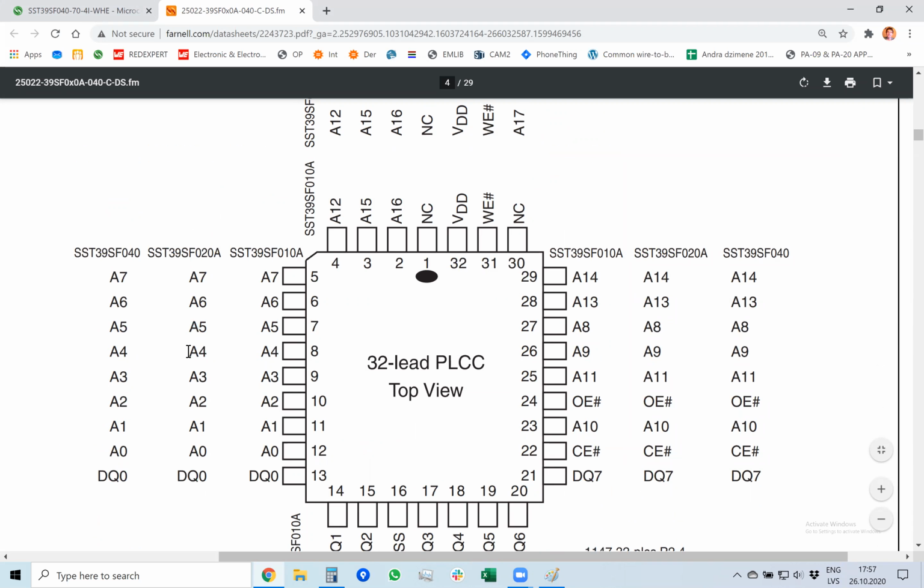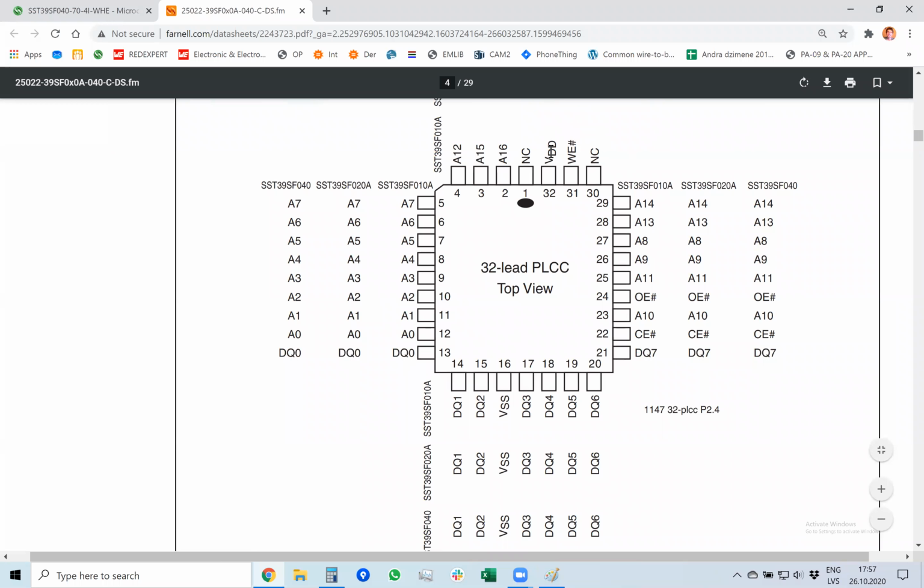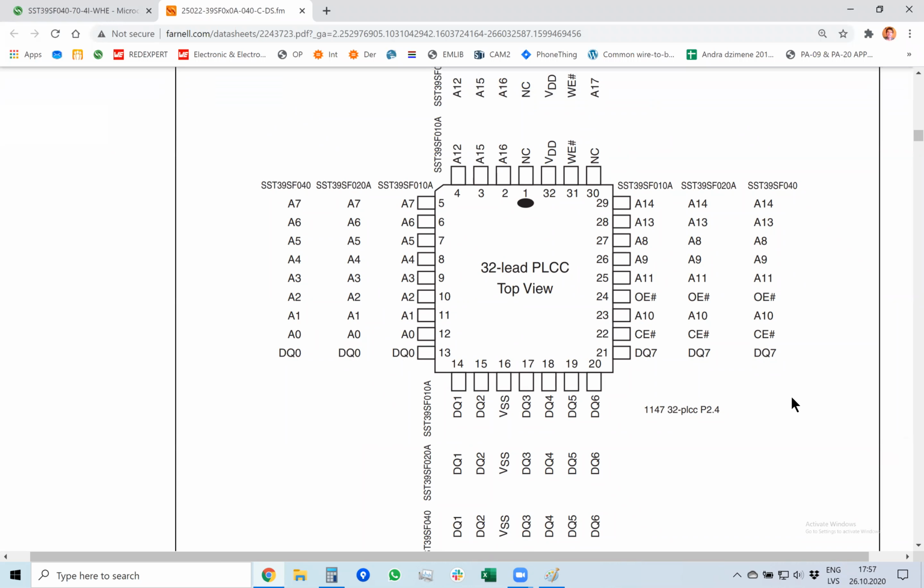Next, as you can see here, it also has data pins, and their name is DQ because D is input and Q is output. So it reads new values or outputs its old values through these data lines, data 0 to 7. So it's just 8-bit memory. It's a regular 8-bit memory. And the control signals, oh, also here's the supply and ground. Control signals are a little bit different, but basically almost the same as what I described.